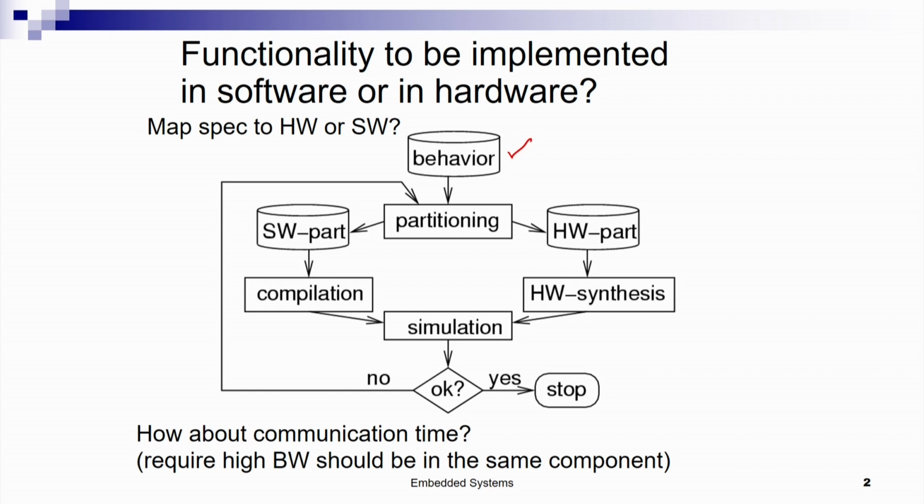Software based implementation could be much less costly than a hardware based implementation. In a software based implementation, you take the C code and push it into a general purpose processor. For a hardware based implementation, the same functionality has to be synthesized and then fabricated, and then you have to obtain a chip for it, and then you get that functionality as hardware. So, it is both costly as well as time to market. The advantage is performance, and maybe size, as the size of the circuit implementing that functionality will also be much lower than that for its software based counterpart.